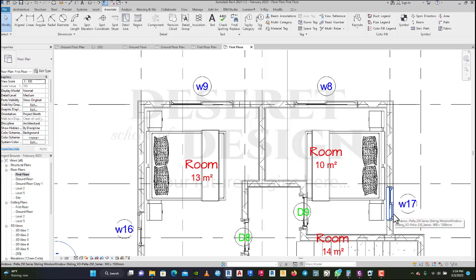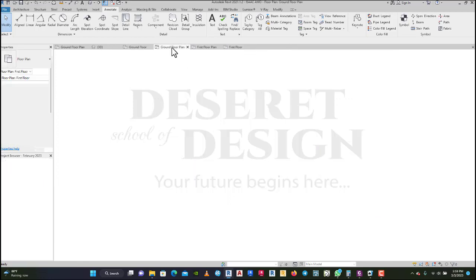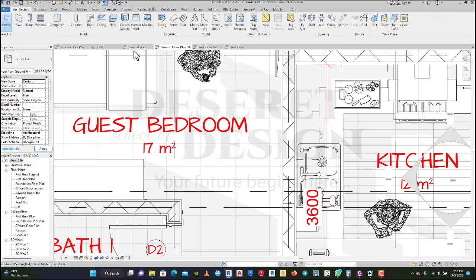Do you get it? Maybe you've placed windows, you've deleted, you've placed. Remember that Revit will still be counting the number of windows you've placed. Whether you've placed or deleted, it will not say, okay, since I've deleted 5 and I brought another one, it will give me 5. No, it will give it as 6. You do get it? Okay, so the numbers you see are the numbers for your tags.